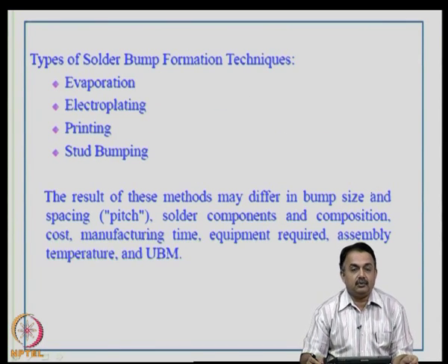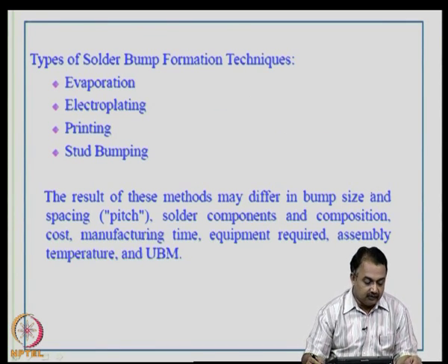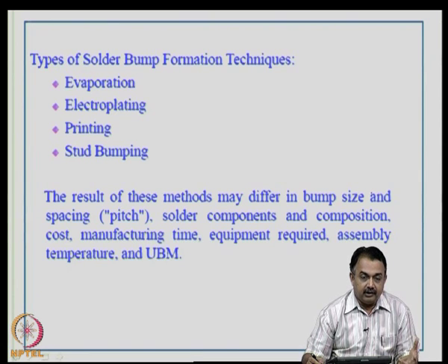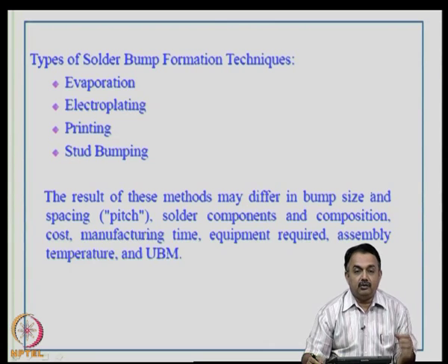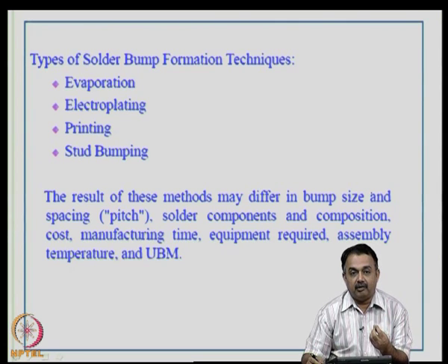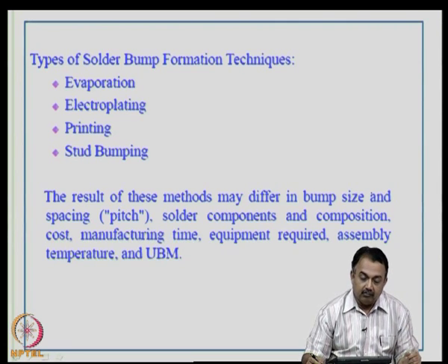The methods to realize the solder bump in these flip chips include evaporation techniques, typically chemical vapor deposition or evaporation methods that you are familiar with, and electroplating. Stencil printing is now available today, where you print the solder paste material and then reflow, and during reflow you can see the bump formation without any solder bridging because of the surface tension property of the solder.